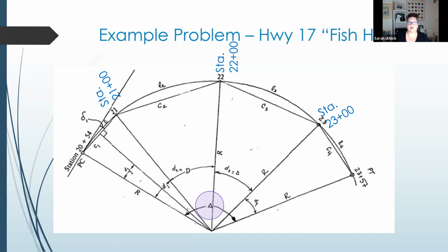Next step. How do we go about finding this entire internal angle? Because we need that information in order to figure out what our deflection angle is at our point of intersection, right? Because it's the same as our internal angle. Without going out and measuring all of that information, we can do it mathematically. We can do it here on paper.